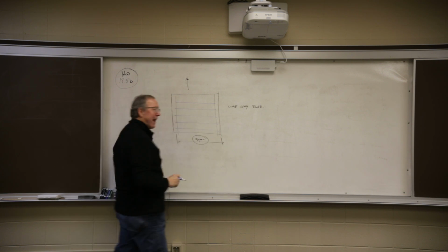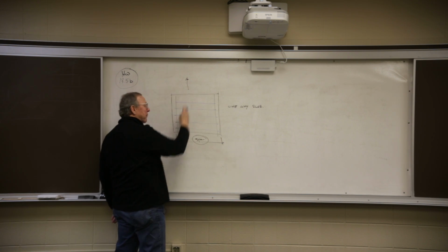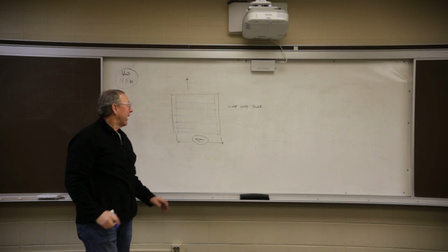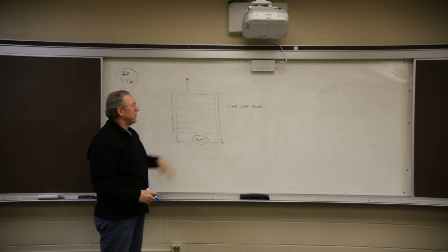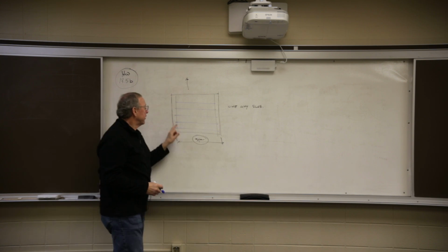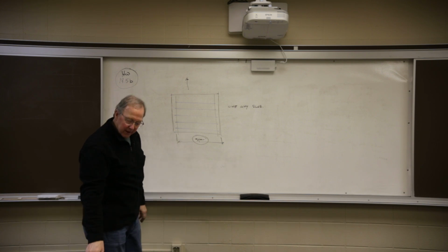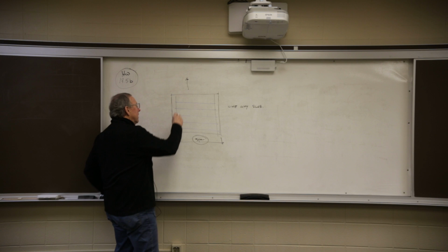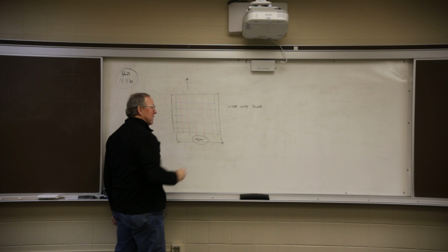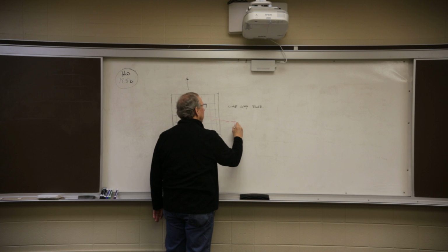On a two-way slab, it's more square, and we would run main steel both directions. We're not going to address that in this course. All we're going to worry about is the fact that it's a width that is much shorter than the length, classified as a one-way slab. Reinforcing steel main will go across the span, and then you will have steel going this way also, but that is not going to carry load. So this is called temperature steel.